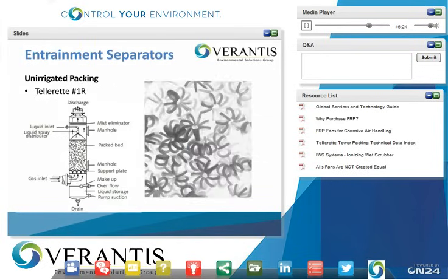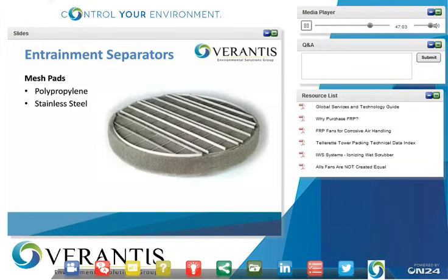Entrainment separators or mist eliminators, there's three different types I'll talk about. These sit, again, above the liquid distributor. We have, in the past, designed unirrigated packing using our number 1 Tellerette. As the mist is carried up into the top of the scrubber by the airstream, the droplets collect on the Tellerettes and form larger droplets, which then allow gravity to do its job and remove them down. Second type is mesh pads. These are most common. We see a lot of polypropylene or stainless steel. These do require frequent inspection to avoid fouling.